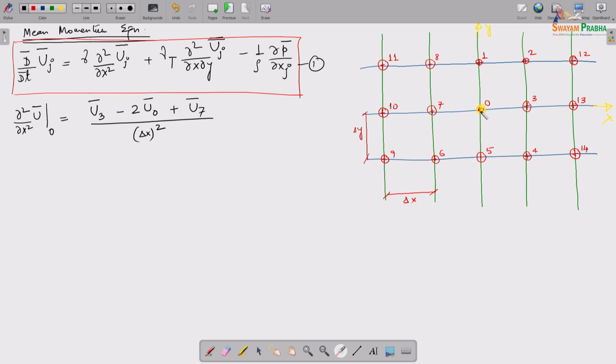So you can ask, well, these are so far apart, why didn't you take something closer? Yes, you could, right, and how you draw the grid and how close they are, how delta x and delta y affect your result, is a very important study, right. Having said that, beyond a point, decreasing your delta x or delta y is not going to help, and that exactly is the limitation of your numerical method.